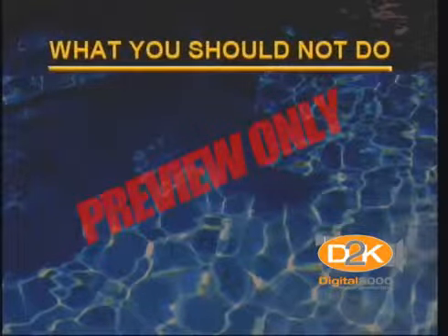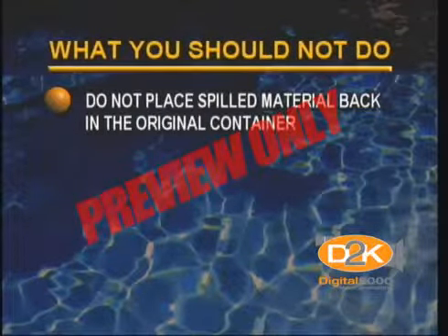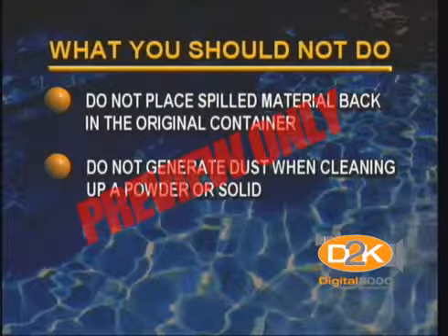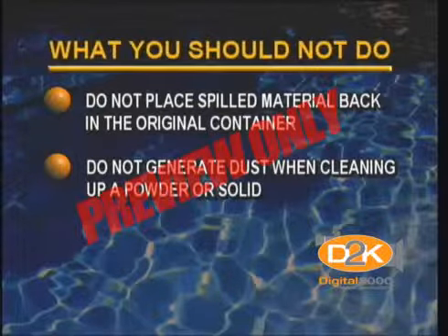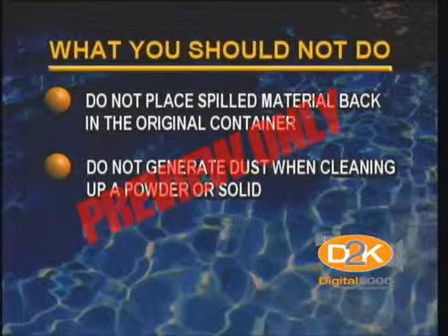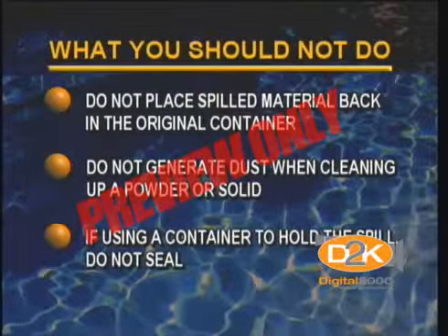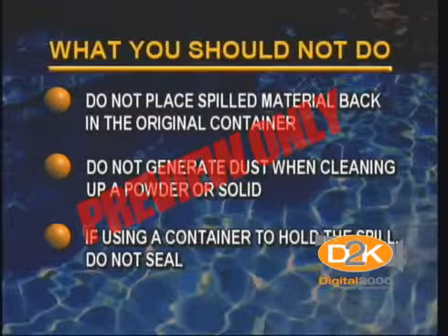What you should not do: do not place spilled material back in the original container. Do not generate dust when cleaning up a powder or solid. The dust may react with the moisture on your skin and cause injury. If using a container to hold the spill, do not seal.